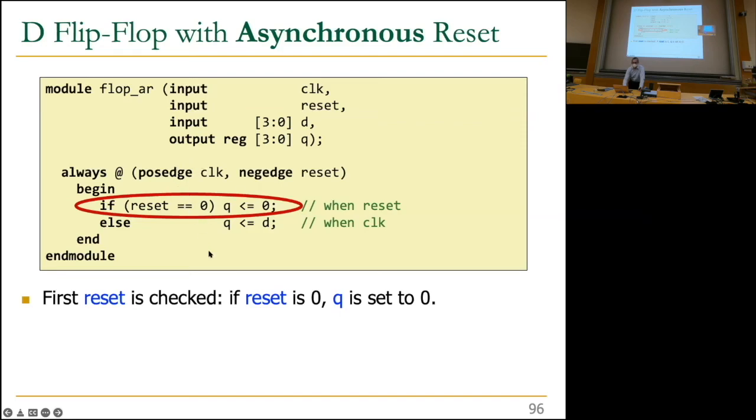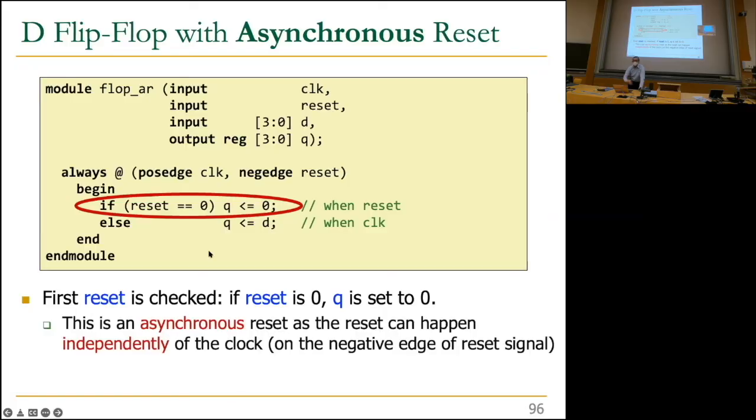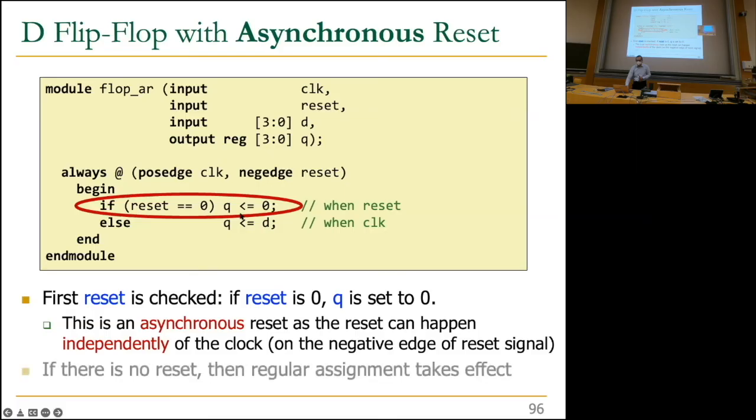Right? You can convince yourself of that. And that's why this is asynchronous. Because reset can happen independently of the clock, on the negative edge of the reset signal, this statement gets executed, and the flip-flop gets reset.